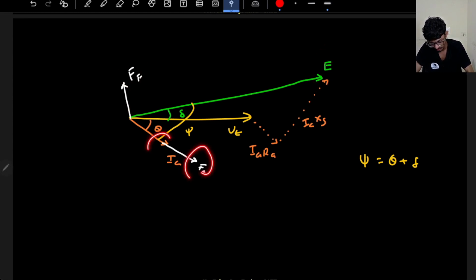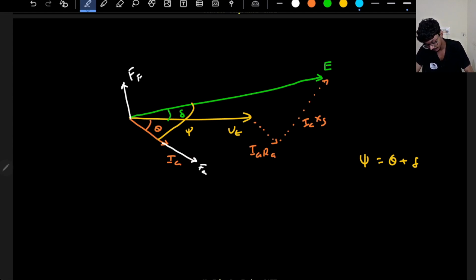What is the combination of armature current and induced EMF? It is the Vt. So this you also have to remember, this I did not specify, that your resultant MMF will lead the terminal voltage by 90 degrees.